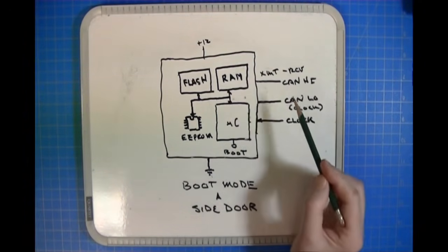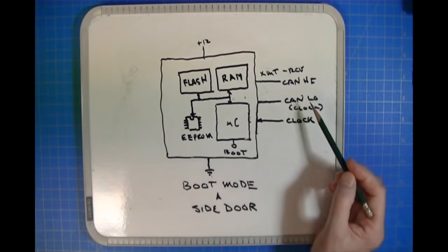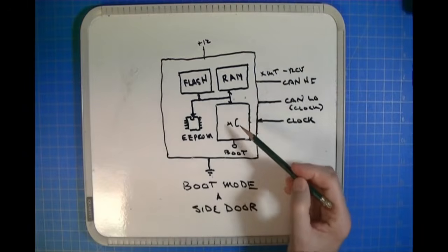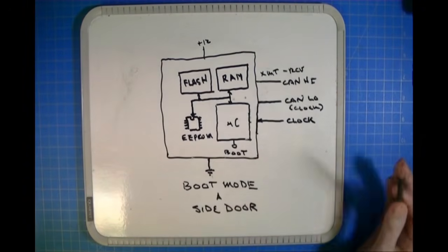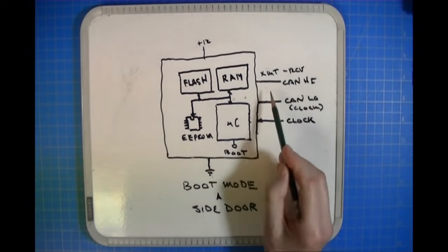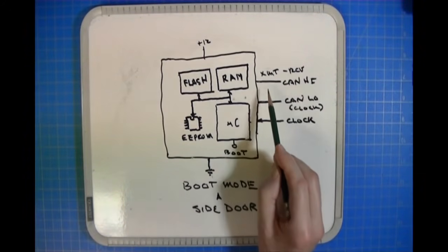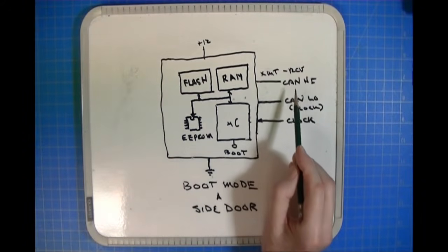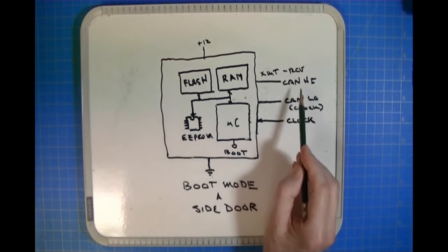Okay, so there's an external program which is designed to do all of the reading and writing and bit manipulation and all of that, which is part of the tool, okay? But in boot mode, it gets brought in over a communication line, which is normally a CAN line, but it's not a CAN command, okay?